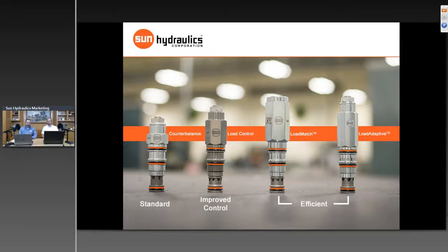Okay, so you mentioned something about a valve that's oversized. So the question I have for you is, I have a specific capacity of my system. I know what that capacity is, but as I'm looking at counterbalance valves on your website, maybe there isn't one that happens to be the exact capacity I'm looking for. Do I oversize the valve or undersize it? It is always safer to undersize. Always safer to undersize the valve.